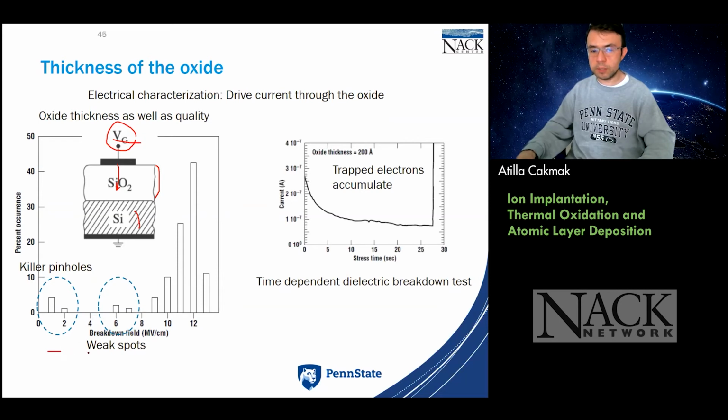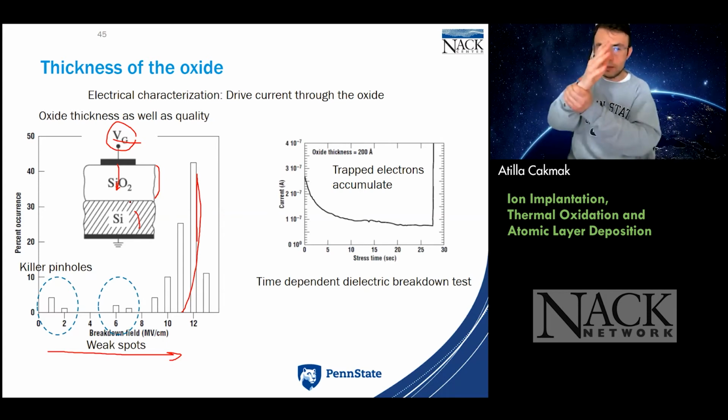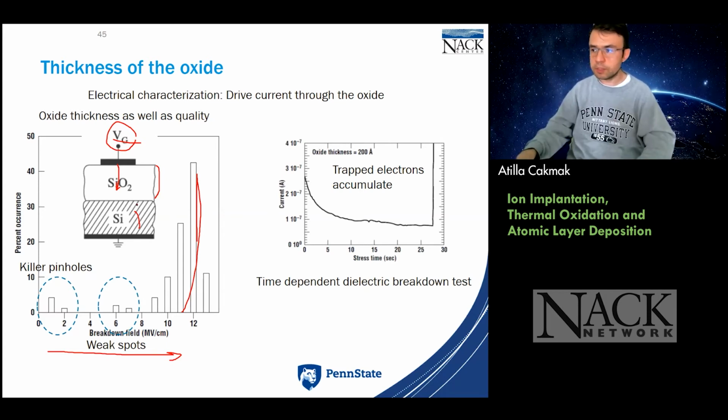So you see that we're increasing the voltage in here in this axis. All of a sudden you break down, that's what we call it, you break down the oxide. That insulator is so much forced that you will just run the current through this, okay? Based on the voltage where this happens, you can understand that's the voltage corresponding to it, so then I have a correlation. If it's thicker, of course, its breakdown voltage will be larger, right? So for these kind of examinations generally.